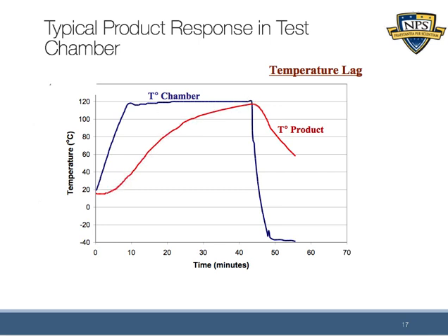And the idea when we run these thermal tests, because of the way that our models work, is that we assume temperature extremes. If we're looking for an acceleration factor by using 120 degrees Celsius, then we have to make sure that once we do our modeling with our Arrhenius equation, or the Norris-Landzberg, or the Coffin-Manson, and we assume the value of 120, that's what's in our calculation.